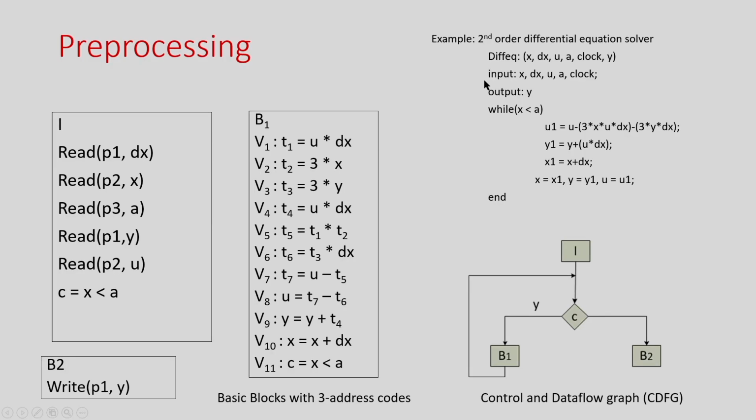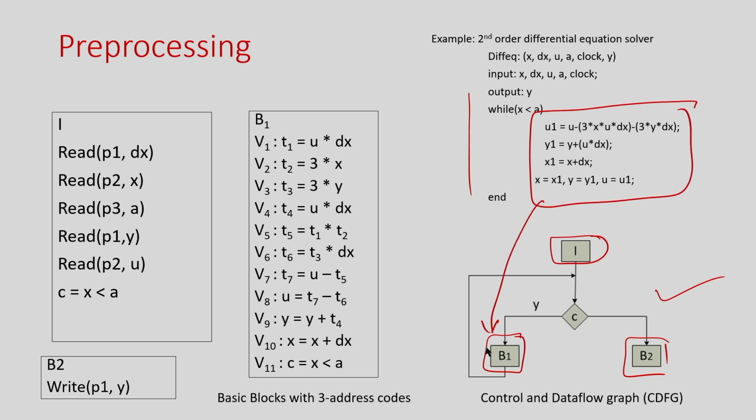And then we can have a schedule of the complete operations, right. So, for example, this is the example I have taken in the last class, that if you have a while loop like this, we have extracted the CDFG where this is a basic block, this is the basic block within the while loop, and this is the basic block at the end, and this basic block represents this code, right. Throughout this class we will take this particular behavior and discuss all these algorithms for scheduling and then allocation and binding with respect to this example, right.